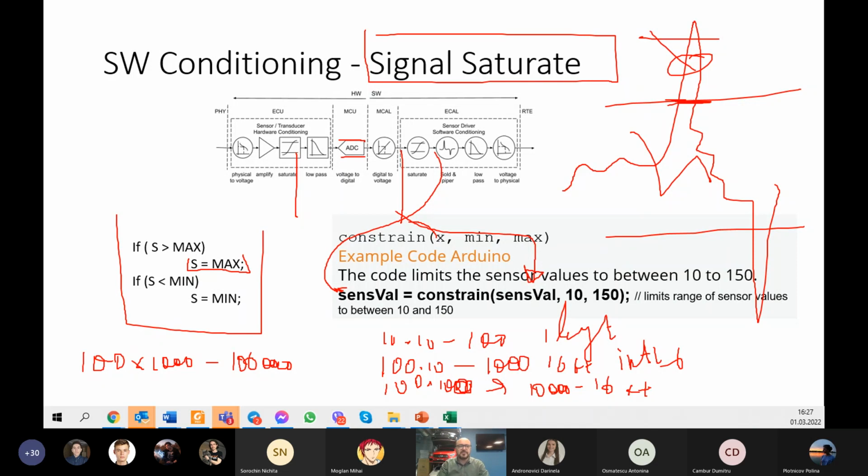So, saturation. Please give me some feedback from 0 to 10 about whether you understand why we need some saturation here and how we are doing that. So we want to protect against high values in the formula, to save the memory and to not have overshooting or overloading, because this value will not fit the 16 bits, and we will have an overload or overshoot. So how can we do that?